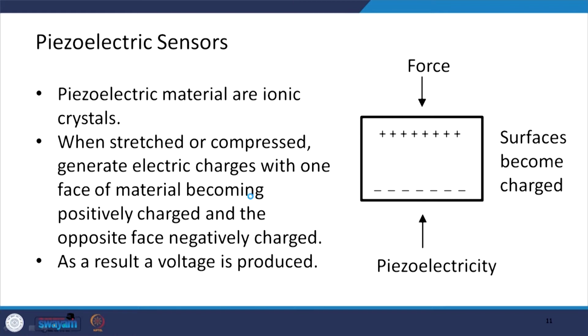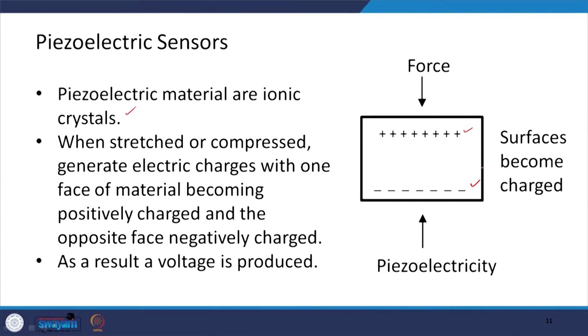These devices use piezoelectric material, which are basically ionic crystals, and when these crystals are stressed or compressed, there is a generation of electric charges, with accumulation of positive charges on one face and negative charges on the other face. As a result, a voltage is produced.